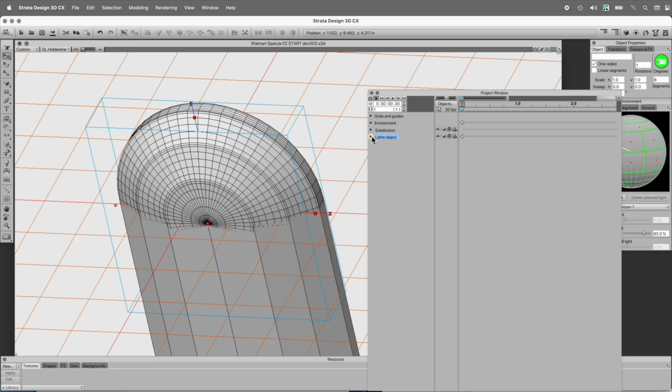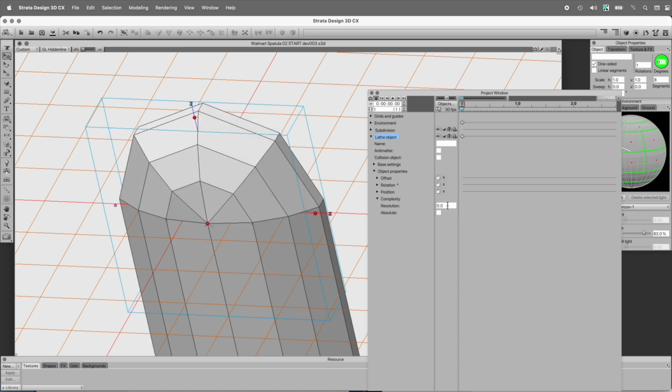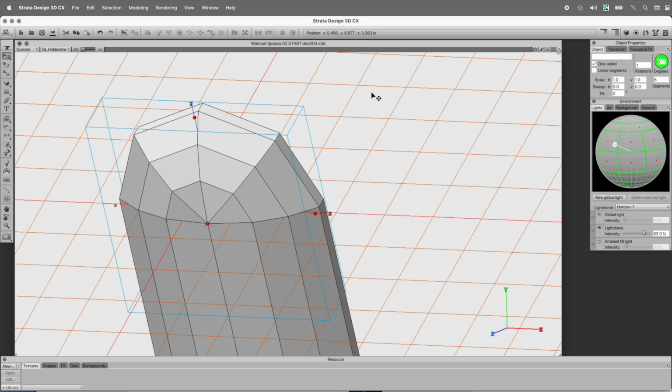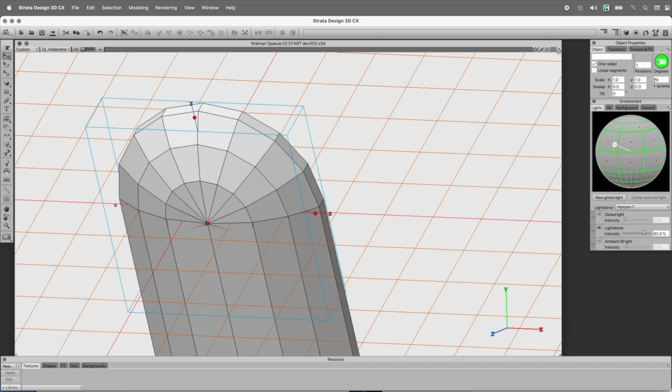Press the P key and let's come down to Object Properties, and let's come over and add in the wing menu a complexity attribute, which we see appear down here, and then we just set that to 0. And that just means it will create one polygon per spline patch. And then we come back over here to the Object Properties. Let's increase this to 16, and you can see that increase.